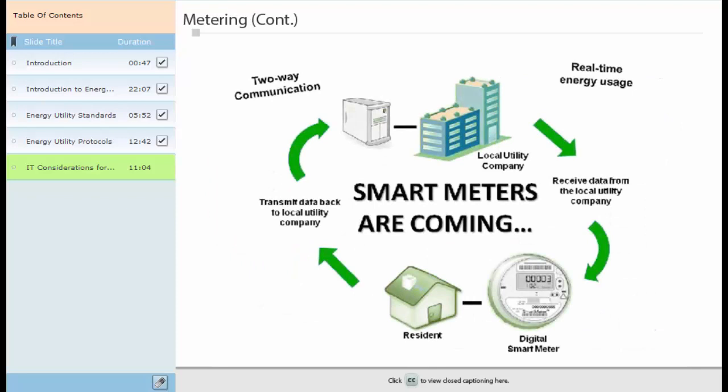While there are many advanced metering devices available, there is a difference between advanced meters and smart meters. Advanced meters are typically developed with a customer or end-use focus. They measure and record interval data and transmit the data to a remote location. Advanced meters offer a variety of measurements, recording intervals and communications options. For federal compliance, measurements of power, kW, and energy, kWh, are important. Beyond these, the options expand to potentially useful diagnostics within the monitoring of voltages, currents, power factor, power quality, and statistical capabilities.